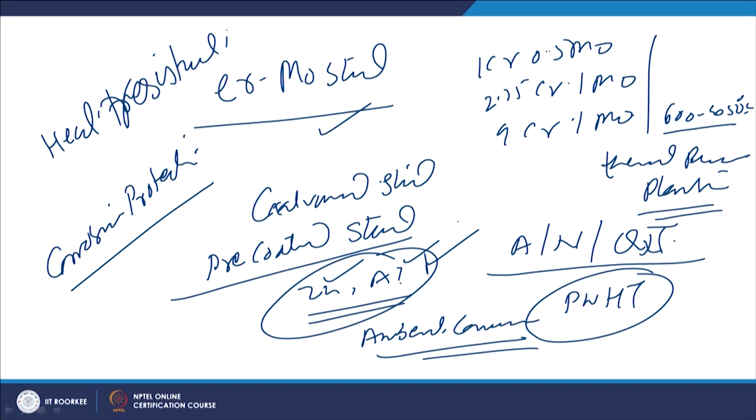Now, I will summarize this presentation. In this presentation, I have talked about how the weldability of metals is affected by the various strengthening mechanisms, and what the various categories of steels are which are grouped on the basis of welding. There are 6 categories of steels, and this categorization is based on the composition, mechanical properties, heat treatment, corrosion resistance, and heat resistant applications.